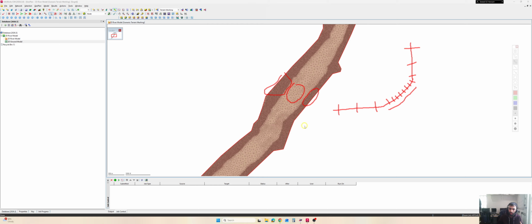So this is how we can change the resolution in InfoWorks as well. For the river model, we can use a hybrid approach. If you say that you want the whole model at high resolution, you can do that, but obviously this will take a long time depending on your system, the PC and the GPU you are using. But I would say that the hybrid approach is the best approach for this system. So you can use this to generate a resolution mesh.